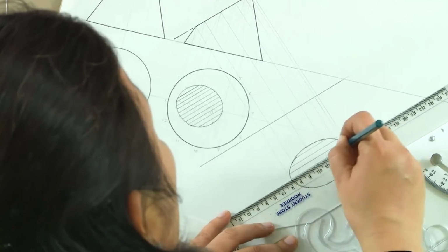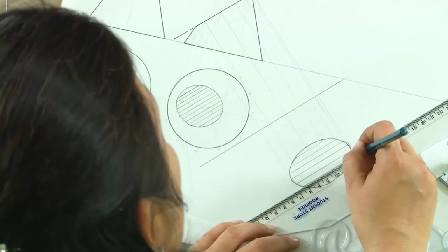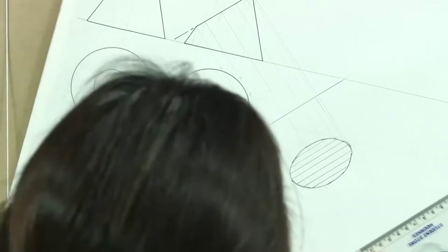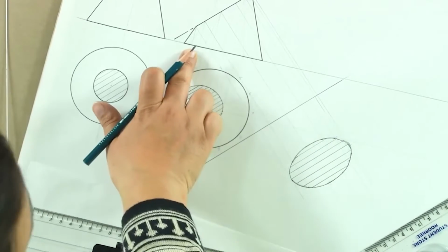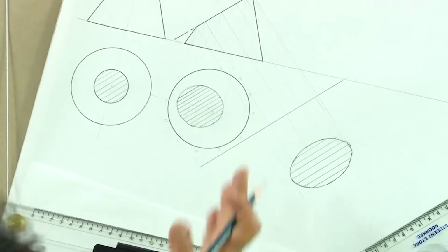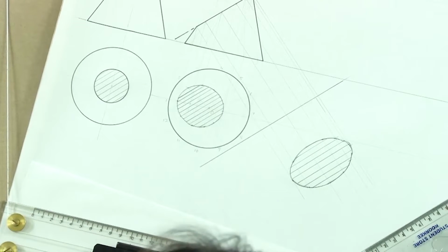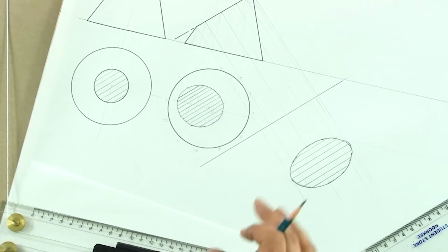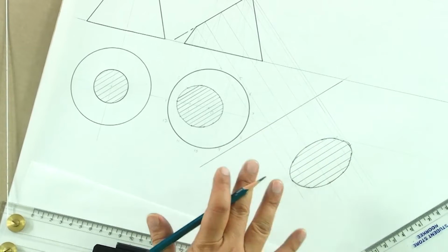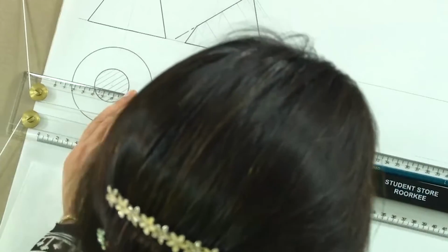So that is what we get when we have a section plane which is inclined to the base of the cone and it is not cutting the base or the apex. So if it is cut in between, we will always see an ellipse, which is what we had explained while we were discussing the conic sections as well as when we were introducing the sections of cones, sections of different solids. So that is another condition. Now what happens if this cone is cut by a section plane which is perpendicular to the base and parallel to the apex? So let us quickly draw the projections for such a case as well.